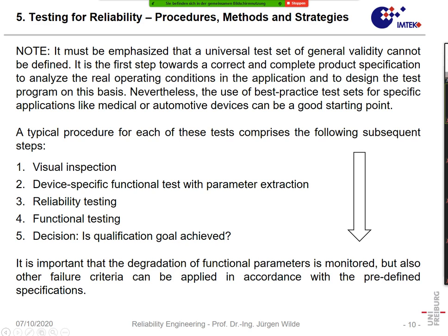Okay, what was the reason why that anti-brake locking system failed? This is a hydraulic system, and that system has an internal pressure, and you need a pressure sensor for sensing this. And in fact, due to a misconstruction, during operation, the 0 point of that sensor could change. So that means normally if there should be a 0 pressure indicated, now it indicates a certain pressure because the 0 point is no longer okay. And that was the reason why this complete anti-brake locking system had a malfunction, and these accidents resulted.